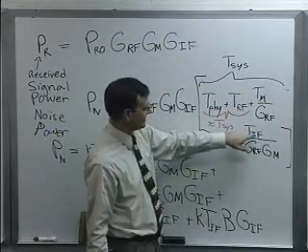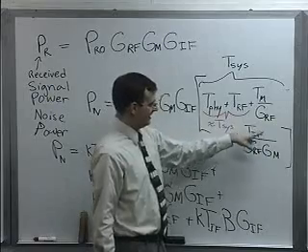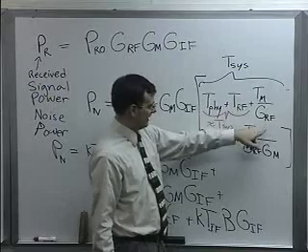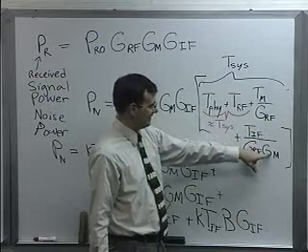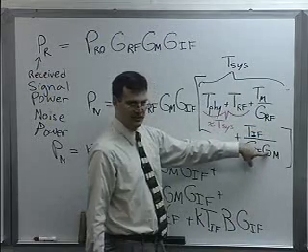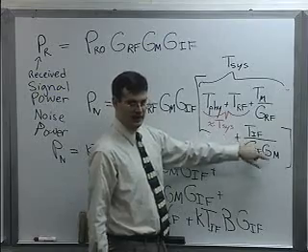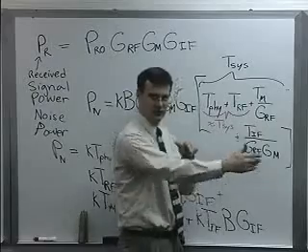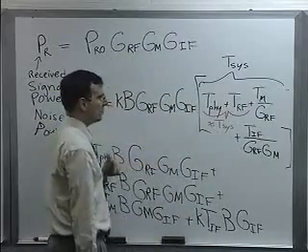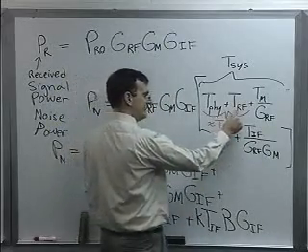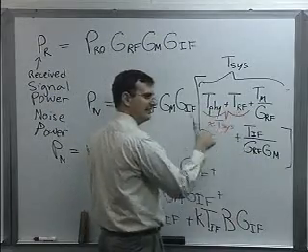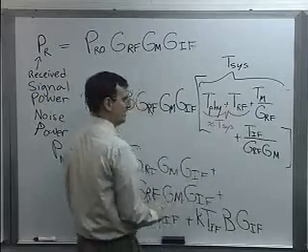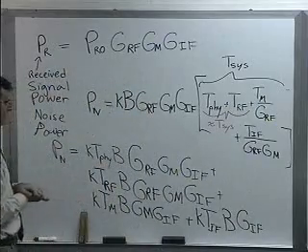And my next in-line device would be a mixer. Maybe it has a noise temperature of, I don't know, 30 Kelvin, 40 Kelvin. Maybe it's not that much. But loss here kills you. If G sub M is less than 1, then it amplifies the effect of that device noise instead of contracting it later on the RF chain. And so that's why that first device right there has got to have some gain, and it's got to have T sub RF as low as possible. And that's what we're always after in design.